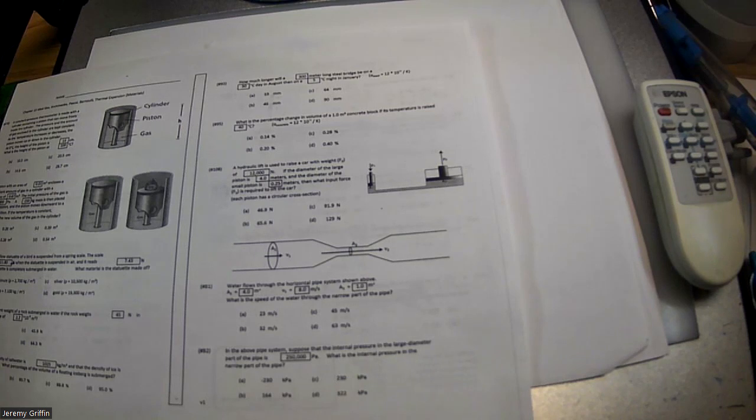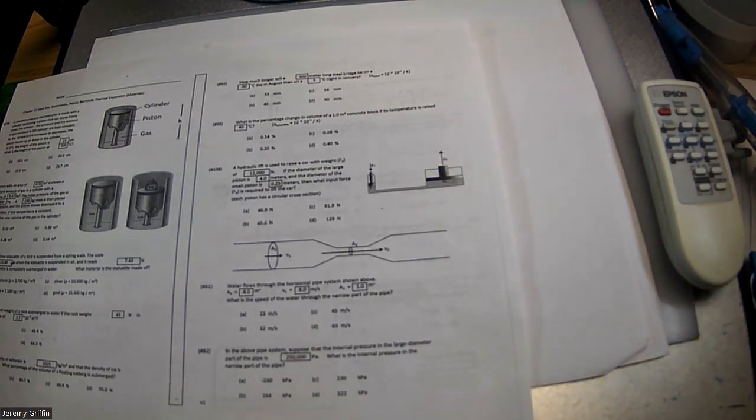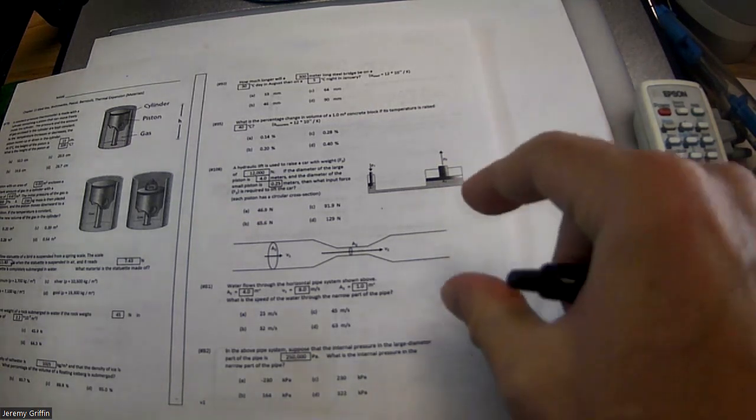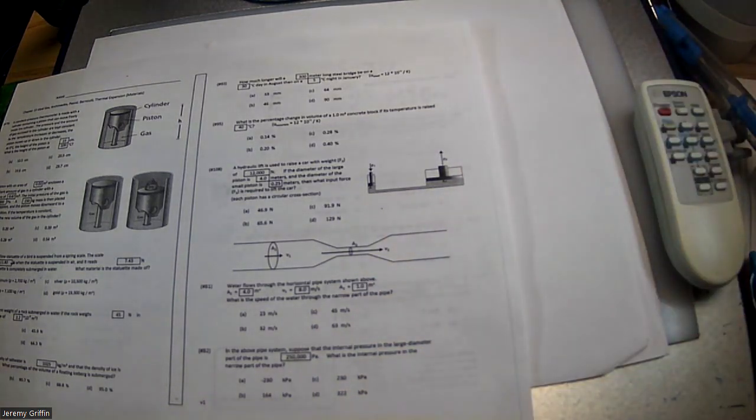You can become a lot stronger, but by doing what? By pulling lots and lots and lots of string. Remember, for a pulley system, you might pull like 5 meters of string, and then the output, that huge weight, only lifts like a meter at a time. So it was really like a conservation of energy type thing.